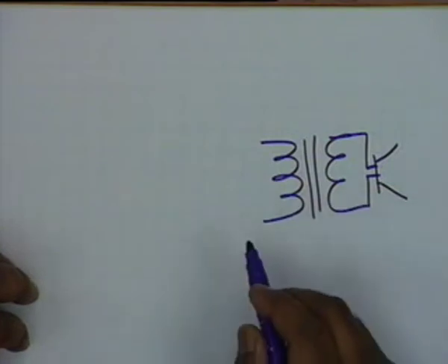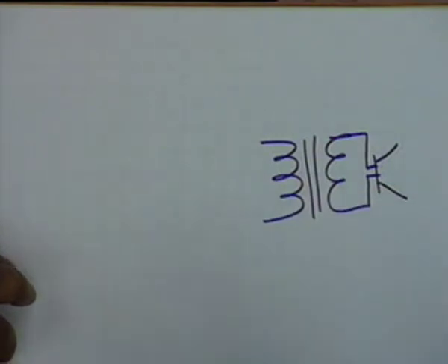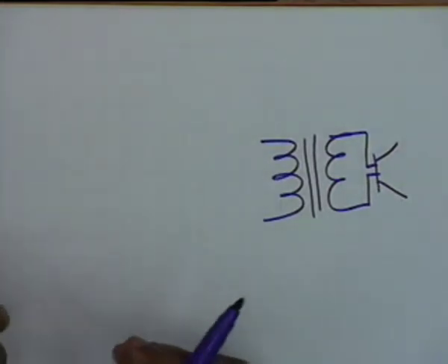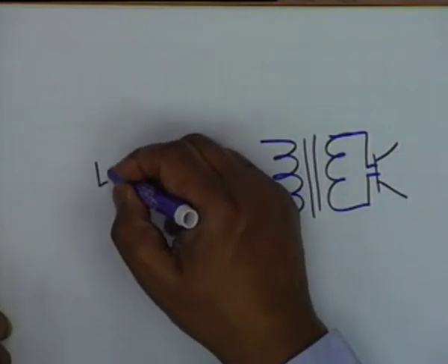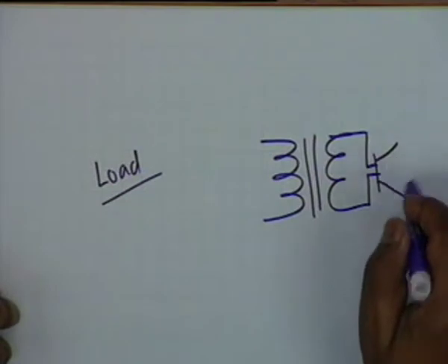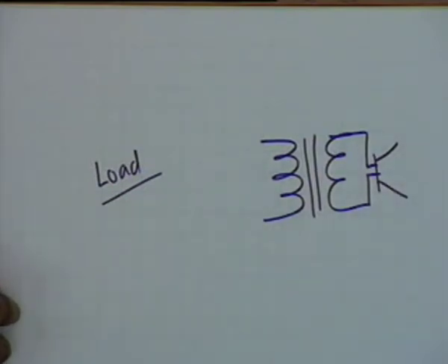Okay, this is called transformer coupling. Coupling is an important consideration in amplifier design. Then the nature of the load. Obviously the load can be resistive, can be inductive, can be capacitive, all kinds of loads. For example, a loudspeaker is usually considered as a resistive load.